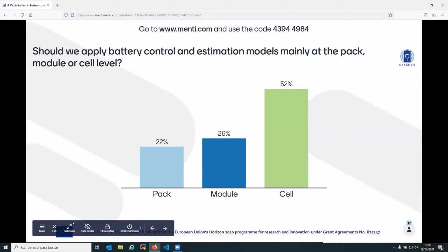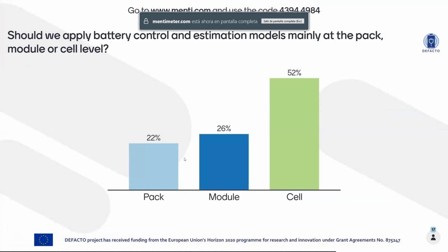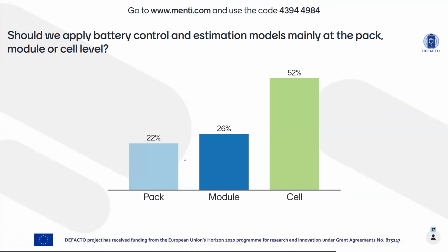Yeah, that's a very good question. And I think it will depend on the cost benefit of deconstructing systems for second life. The systems I've seen, for example, with a company like EcoStore, I think they just take the entire pack from a Nissan Leaf, for example, and reuse the pack. So they don't necessarily pull out individual cells, but if you could make it cost effective to remove individual cells, then you could do cell level second life. But my gut feeling is at the moment, it's too expensive to do that.